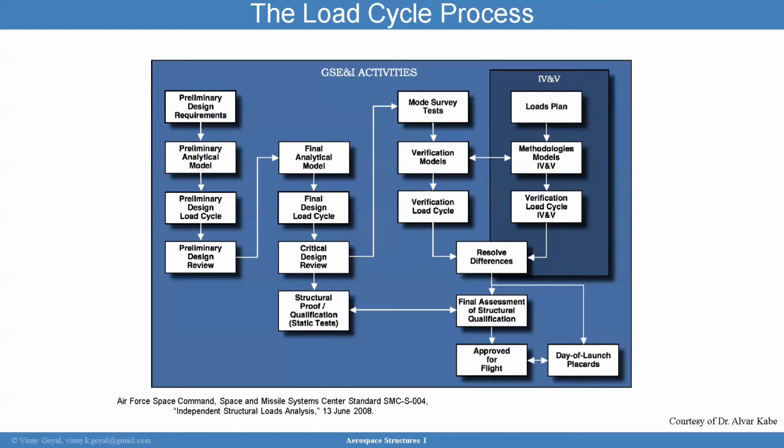These models will usually be reduced in size and are going to give you some amount of information that can help you start developing a better understanding, with the forcing functions, of how the spacecraft will perform when it's attached to that launch vehicle. You don't want that spacecraft to break off due to launch vehicle vibration. So that becomes very important.